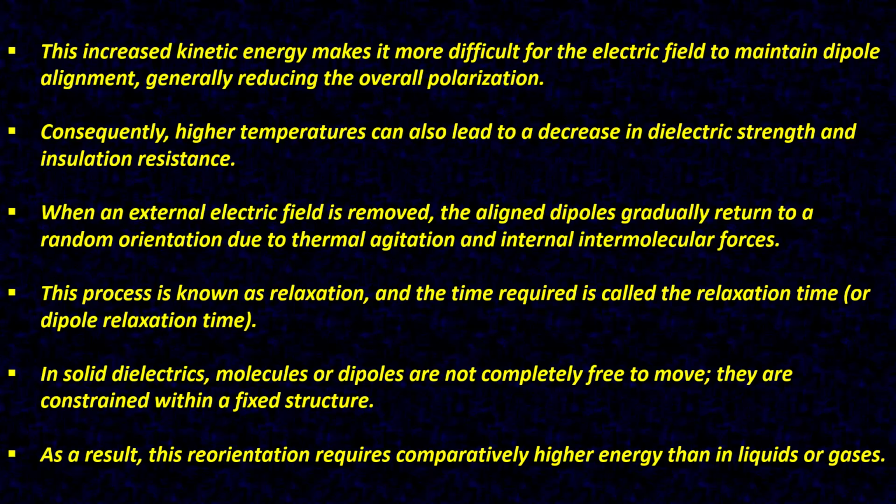When an external electric field is removed, the aligned dipoles gradually return to a random orientation due to thermal agitation and internal intermolecular forces. This process is known as relaxation, and the time required is called the relaxation time or dipole relaxation time. In solid dielectrics, molecules or dipoles are not completely free to move. They are constrained within a fixed structure.